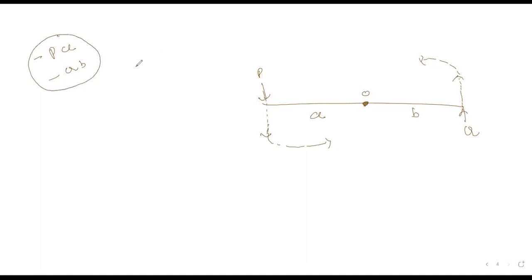How to decide the direction of moment. Now all of you are able to understand how to decide the direction of moment? Yes or no? Yes, sir. Now the question is that one force is acting in downward direction and another force is acting in upward direction. Why will both moments be negative? Is this the question? Yes or no? Until now we had studied that the moment of an upward force will be clockwise, or the moment of a downward force will be anti-clockwise, something like that we had memorised? Yes or no?